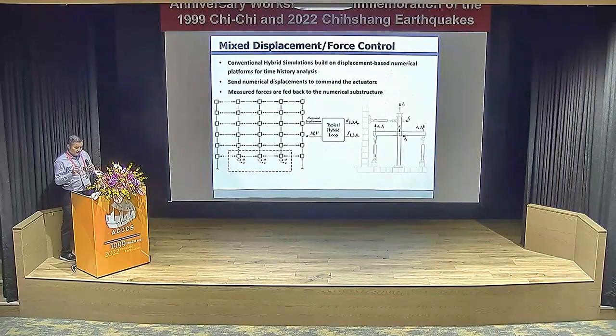Now, we used in the axial load direction, again, when you look at displacement-based frameworks for OpenSees, mostly all finite element programs are displacement-based, where you send displacements to the elements and get back forces. This is the typical framework used for hybrid testing. But in the axial direction, the column's fairly stiff. Displacement control is a little bit more challenging, especially in our case. We were using hydraulic jacks because of the high load that we wanted to apply. These were more readily available in this lab. And so our displacement control was really bad, but with force control, we were able to get a much better match.